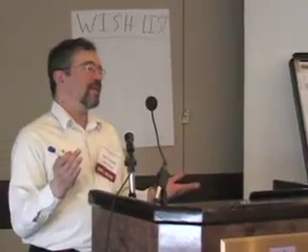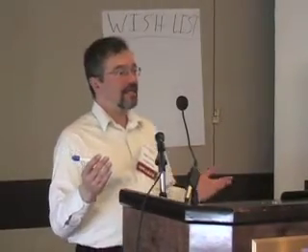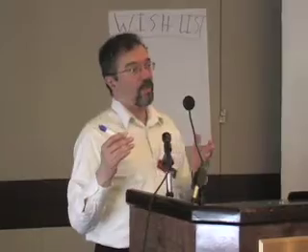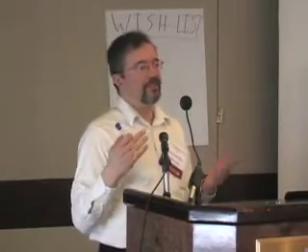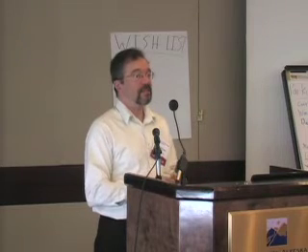Well, so my thinking is this: HOMER tells you what's economic, but it doesn't tell you in that level of detail what's feasible or what's stable. I mean, we use the term feasible, but is it really stable? The dynamic models tell you it's stable, and you can always make something stable by loading on more equipment and more cost.